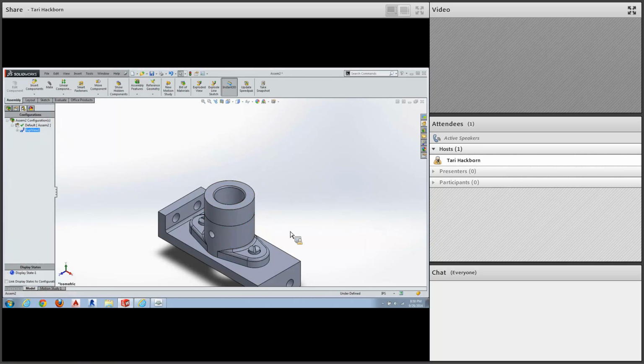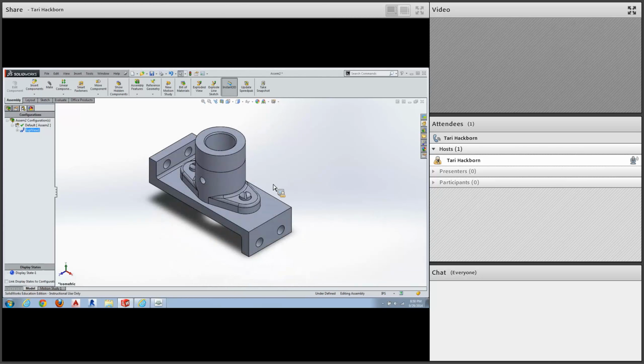Okay. At this point, we're going to end the first part of the assembly demo, and I would like you to create a folder that will say your three initials assembly, and into that folder put this assembly file and put all four parts, the base plate, the bearing, the collar, and the cap screws. Because remember, everything's associative in SolidWorks, and if the part files are not in the same folder with your assembly, when I open the assembly, none of the parts will show up.